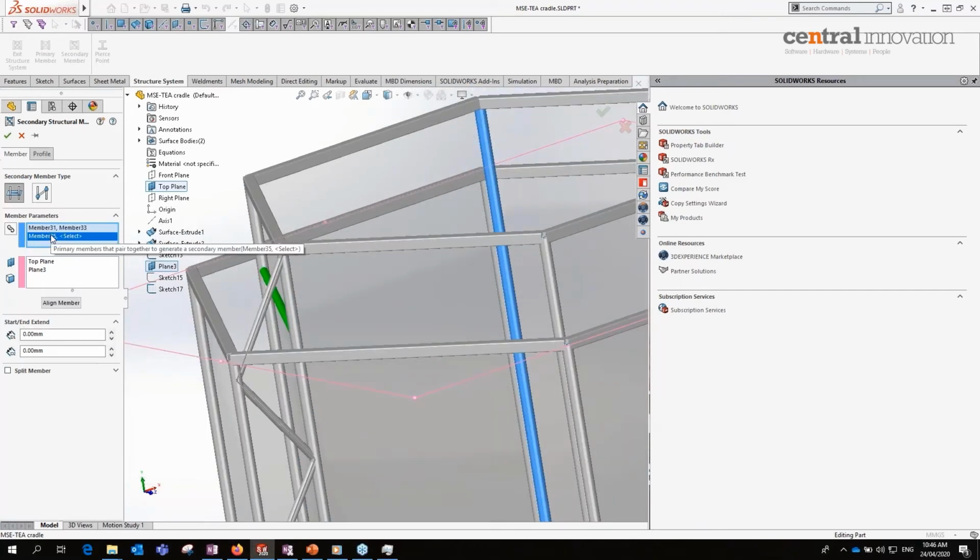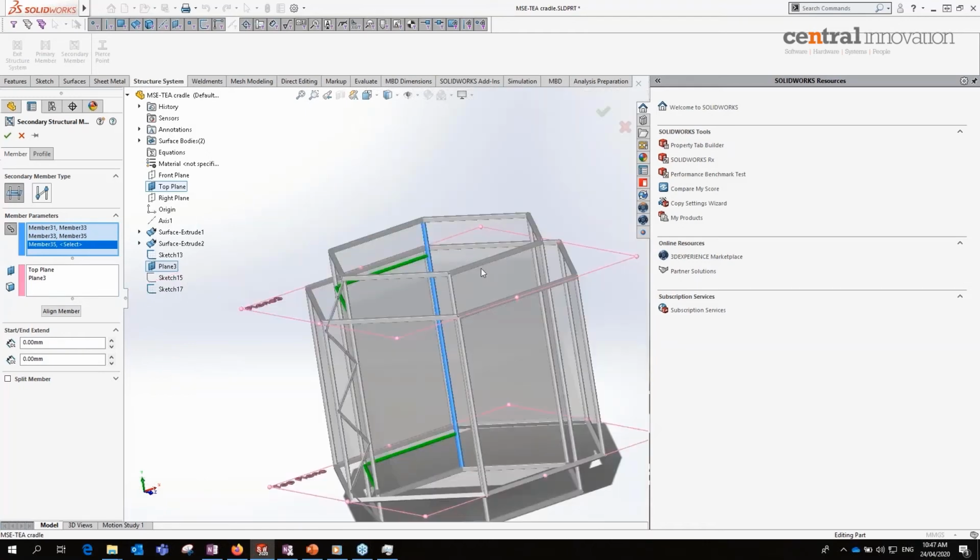Okay, so the issue now was this process that I'm not only creating members between pairs. I want to create members between all the selections I will do, not between pairs. So I will clear the selection, and in this case, you have to toggle a chain selection. So it will be a chain loop, not pair members only. So when I start selection, now it will proceed with the chain loop.